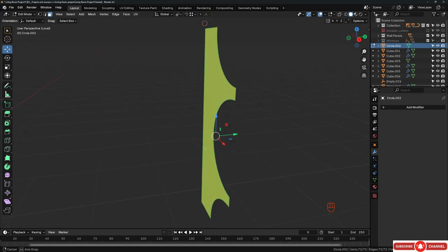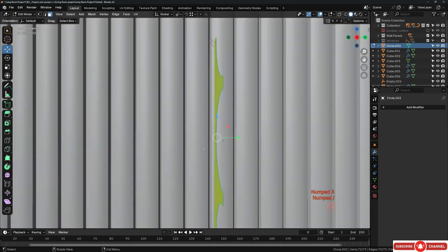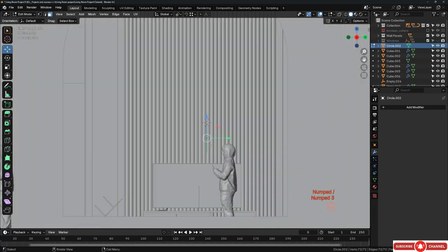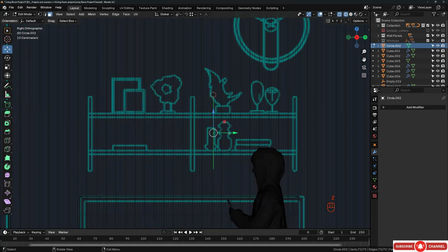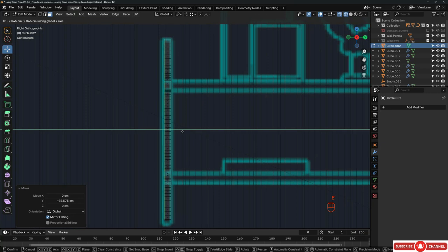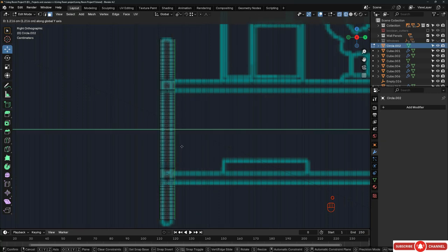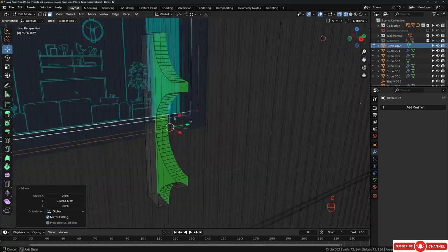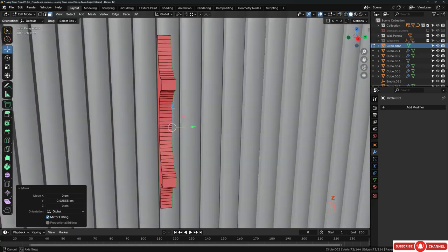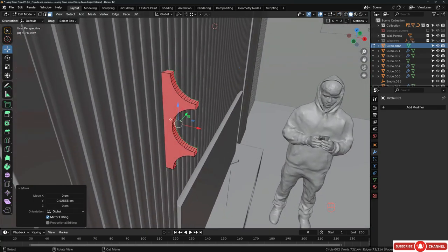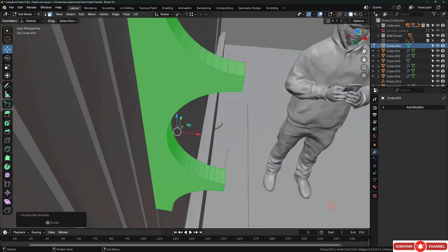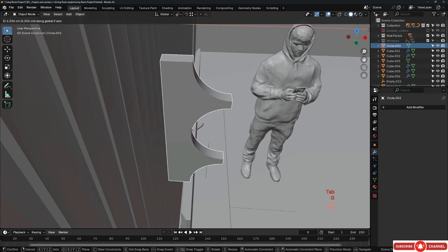to one surface. And from the right view, after you exit from the local mode, you can put this in the correct place. For example, you can start from here, moving this right here, and then you can hit E and extrude this like that. And let's grab this side and move it just a little bit like that. All right, and if the normal flipped, hit A and then Shift N to recalculate the normal. After that, we can tab out and take this out just a little bit like that.